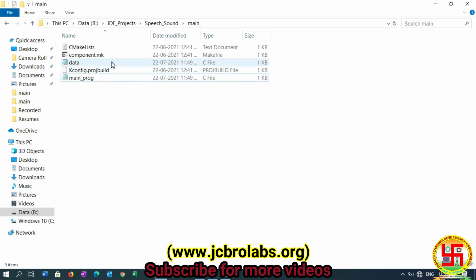In data.c we take a double array and store the speech data in this file, and we generate the data through Matlab. We record the sound, hello hello sound, in Matlab and create a text file, and the generated data is copied into the data file.